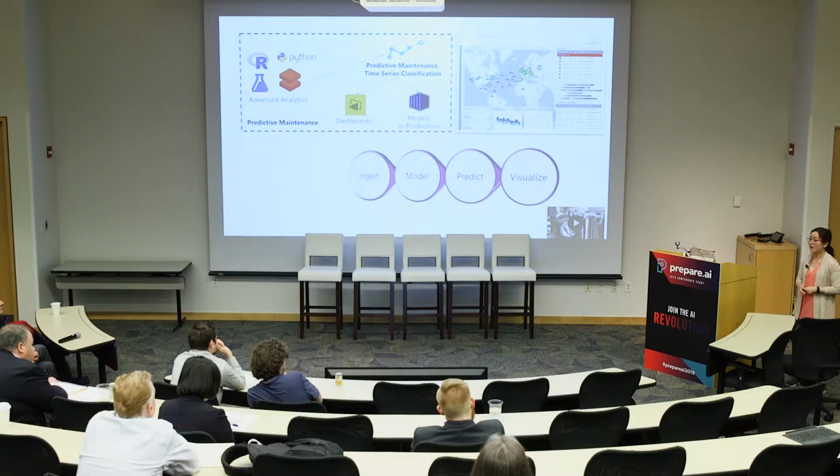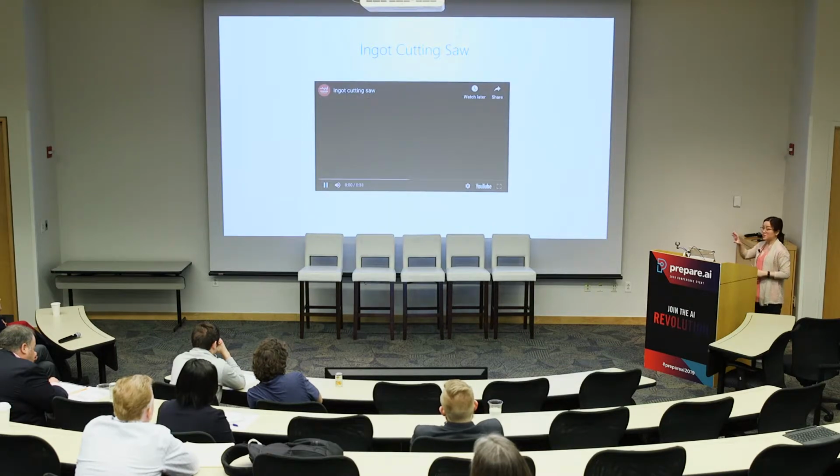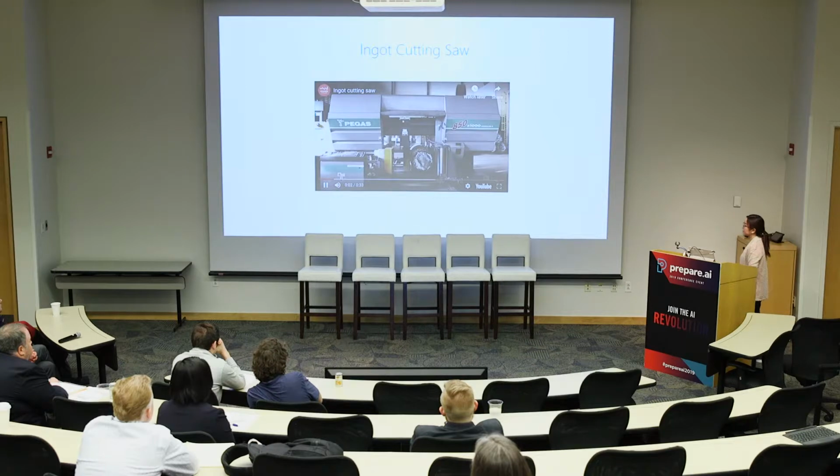So how do we know to maintain the machine, the saw cutting, the engine around it, oil and whatnot, coolant around it, so that it will cut through this block until the end within my 8-hour shift? So we align all this together. And if by the end of my shift, this blade is not good enough for the whole next shift, I better replace it. It's my job to replace it now, so that the downtime aligns with the breaks and the switch of people too. So let's take a look, just to get the idea, and this is considered super small compared to the real use case.